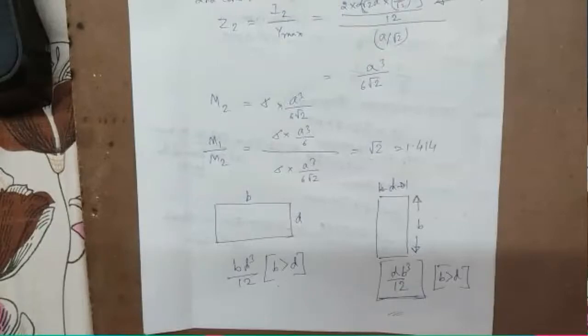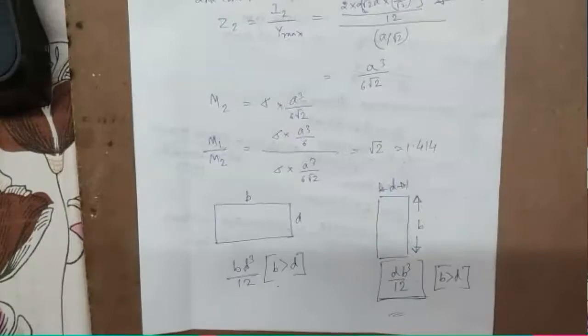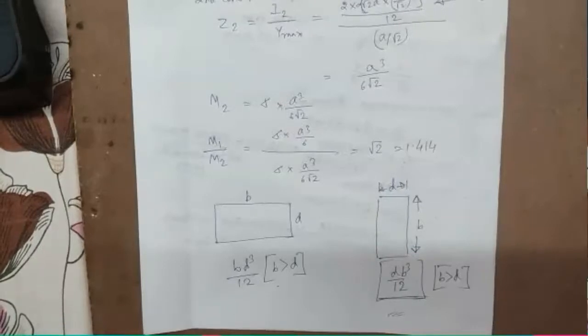So when the designer has designed it, you will find the girders, the long supporting bars under the flyovers. You will find beams are used which have more depth than their width. Generally I section is used. You will find below the flyovers that I section beams are used.